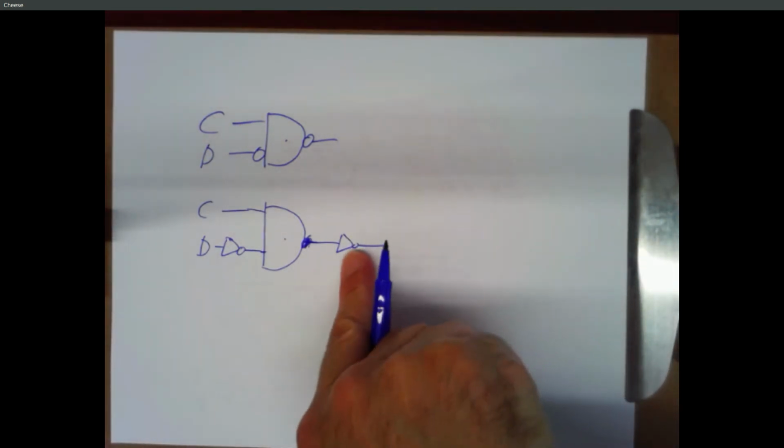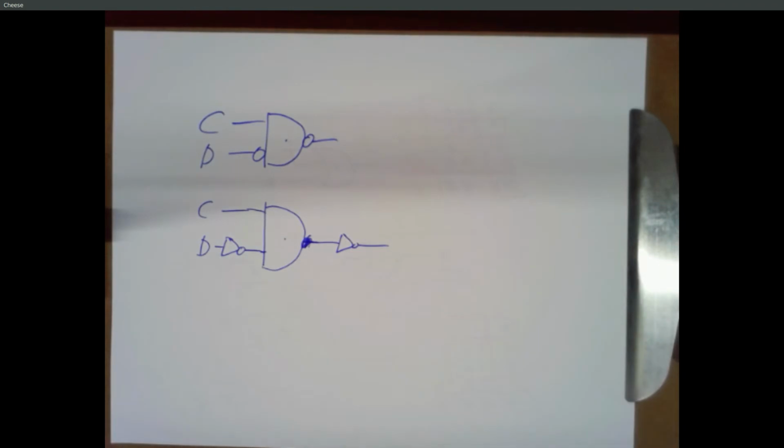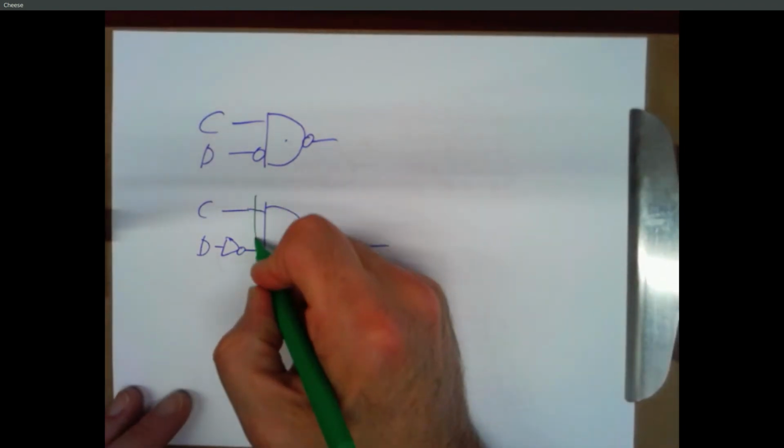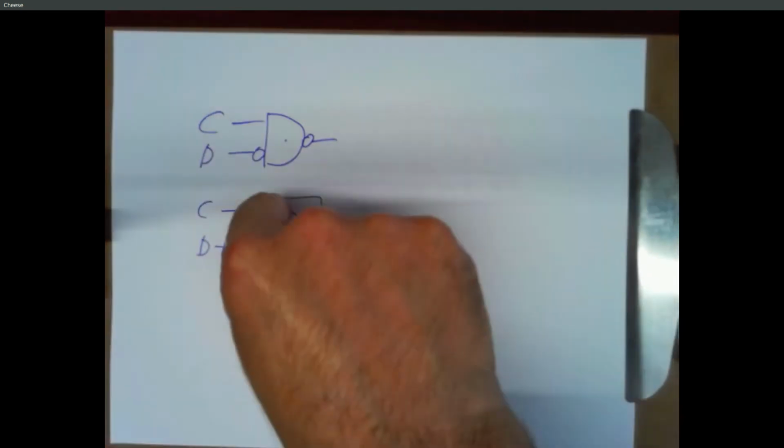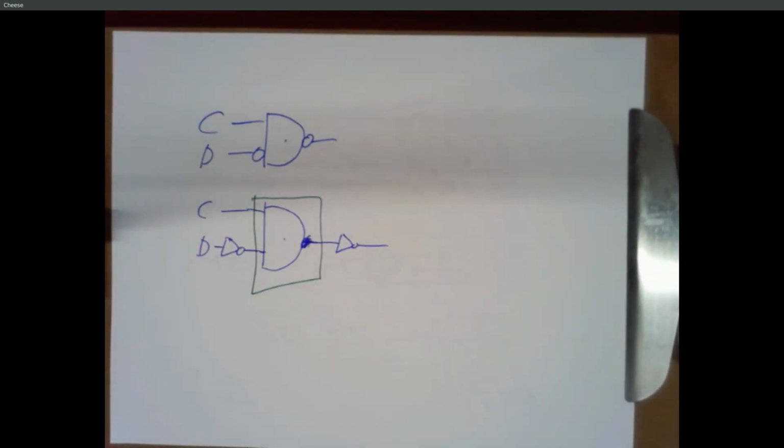Well, there's another inverter we can make. So really, all we got to do is figure out how to make an AND gate out of NORs. If we can do that, we can just plunk that in here, inverter, inverter, and there's our second piece of our circuit.